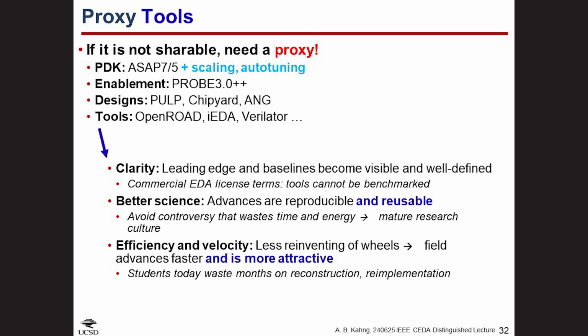The plot shows power versus effective clock period, the hockey stick, so clock period on the X, total power on the Y, for the JPEG design at 9 target clock periods. And the foundry 7-nanometer enablement hockey stick is in gray, and the auto-tuned ASAP7 enablement hockey stick is in orange, where both back end of the line RC constants and cell level scaling parameters like delay or slew or leakage are used in the tuning.